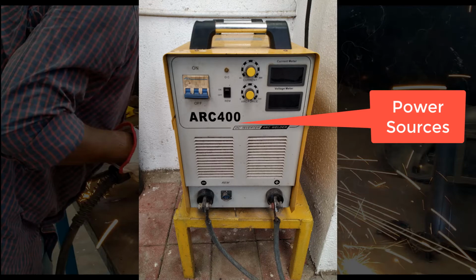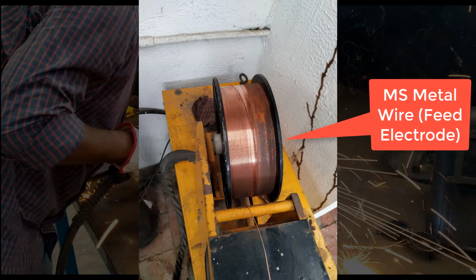The purpose of the power source is to supply the strong current, to convert your current from AC to DC in case of a DC inverter, and also to generate the stable arc, because we are performing the arc welding process, and our process is the metal inert gas welding process. In general, in every welding process we need some power source for generating the heat. Here the DC inverter is used, having positive and negative connectivity, and as per our discussion, here continuously feed wire.